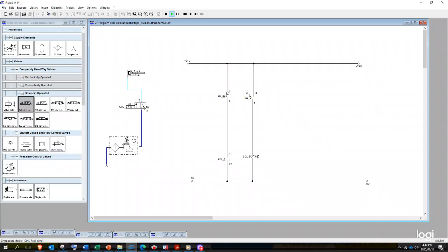In most examples, I like to say a locking blade is released. It's pushing wooden boards onto the conveyor belt. Once you release your hand from the push button, then it bounces back. Why does it do that? In this particular scenario, it does that because of what? Our single acting cylinder has a spring return. Our solenoid valve also has a spring return.